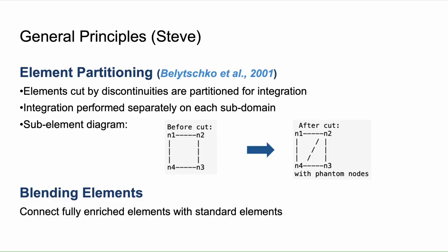Equally important are blending elements, which provide a smooth transition between fully enriched elements and the standard elements. This maintains continuity across the entire domain and ensures that our enrichment is properly localized to where it's needed. So this is the part on the principles of XFEM.